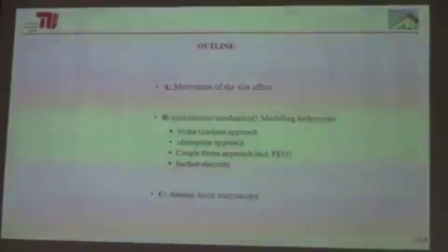My outline is first a short motivation of the size effect in elasticity, and then to present some modeling techniques, such as the strain gradient approach, the micropolar approach, the coupled stress approach and surface elasticity, before I come to an experimental point of view, how to get some material parameters for real materials.